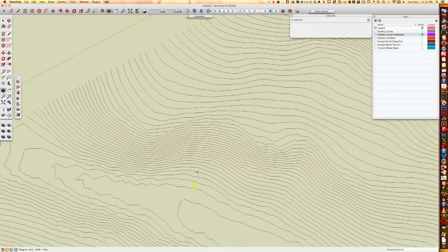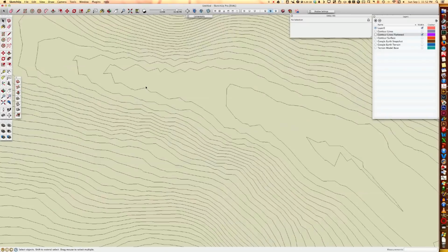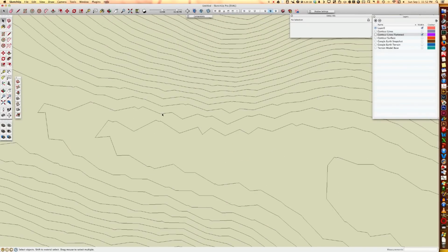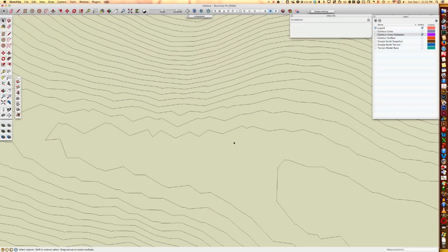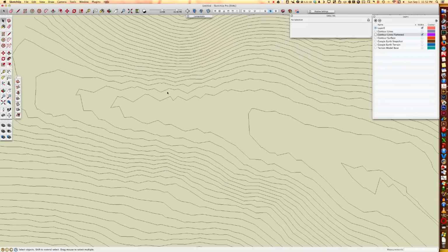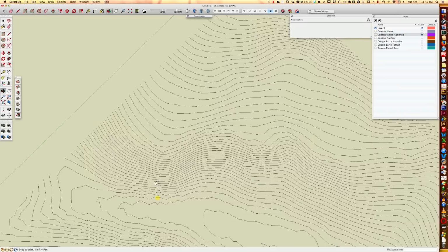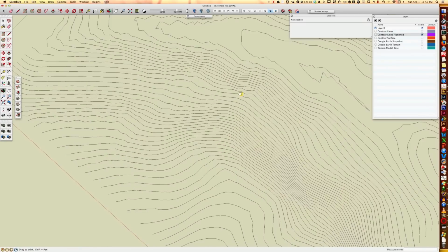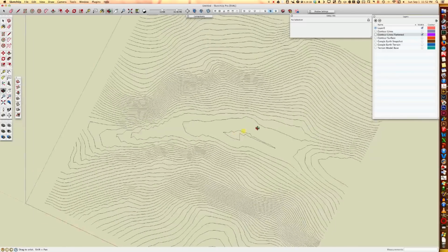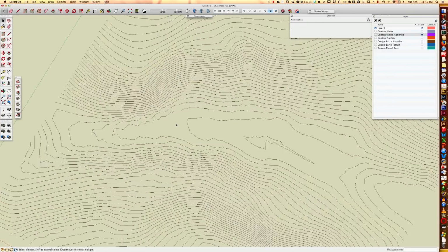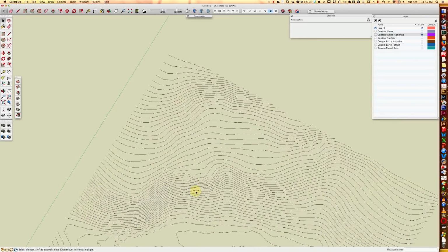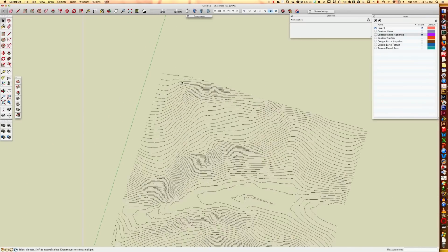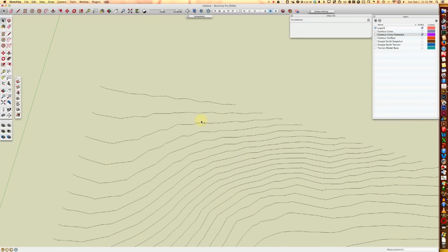Now we're almost ready to go, except that, take a look at the lines here. This is ridiculous. This is not a natural kind of thing. This is an approximation to the curve, and kind of a bad approximation in a lot of regards. So what I want you to do is redraw these things so you get nice lines. And this is where the Bezier Curve tool comes in to help us out.